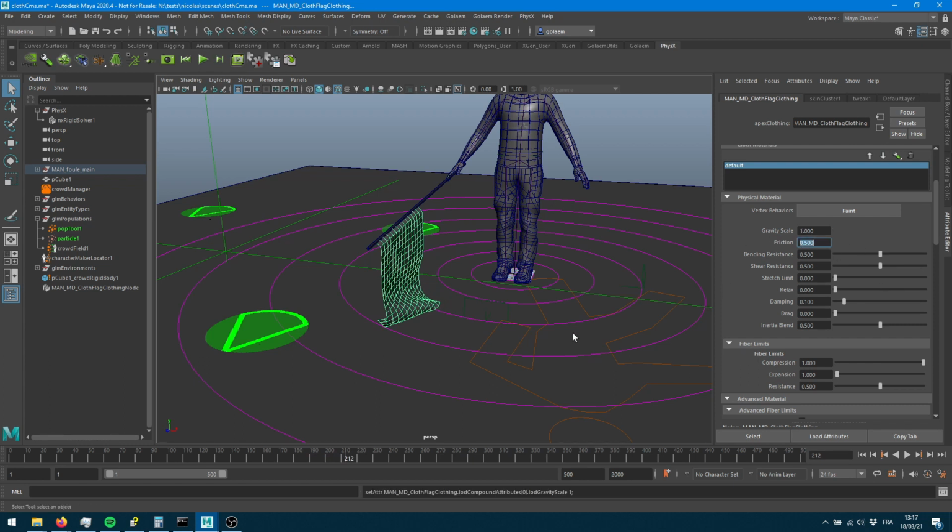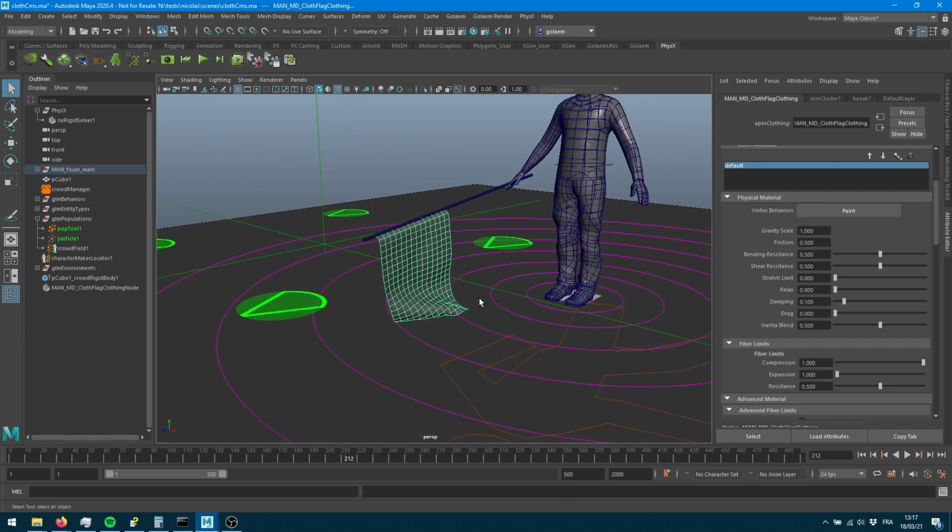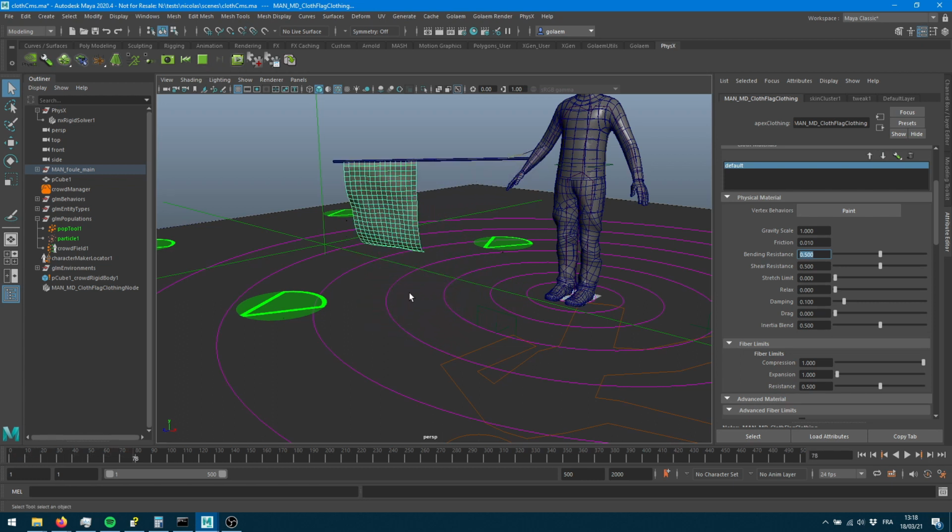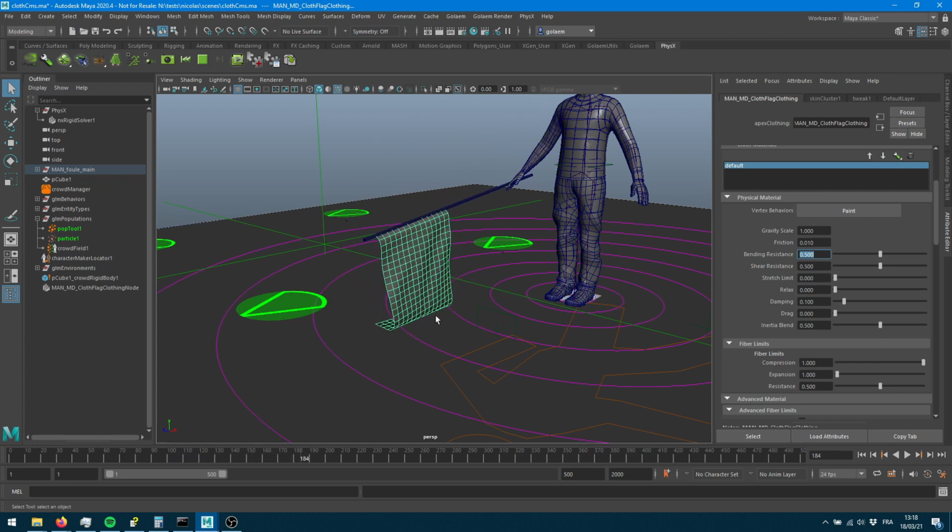Then you've got friction. Friction comes into the game whenever there's a collision with an object. So here in our scene, we're in collision with the ground plane, and every time there's a collision, it's going to slow down the velocity of the clothes. If we provide a really low friction, you can't provide a 0 value, but you can provide something really low, you'll have your clothes which will really glide on the ground. Oops, let's go back in time with this. You may have noticed that it was much more sliding and gliding on the ground. It's like a slippery surface.